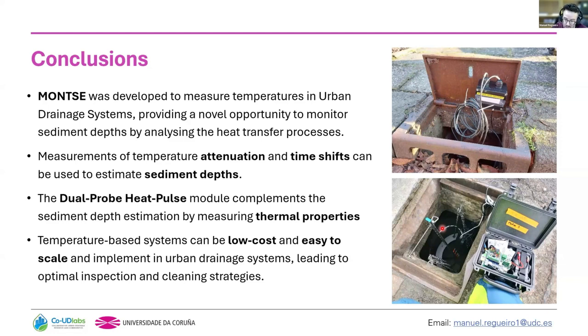So it's also a change of the typical way to understand and approach this sediment accumulation problem, which for example uses other types of sensors or introduces a lot of velocity meters or flow meters. In this case, it's just measuring temperatures.